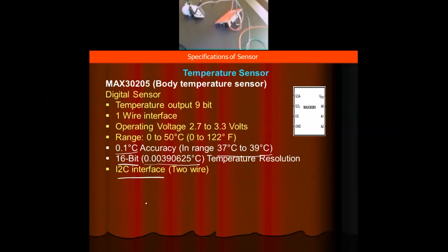It requires the power supply because the operating voltage is written here. You can see VDD is written here, so at this point we have to connect a power supply, and here we connect ground. A passive sensor you can easily identify because it doesn't have power pins at all, and doesn't require any external power.